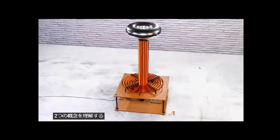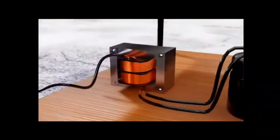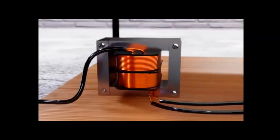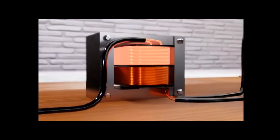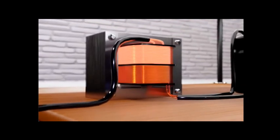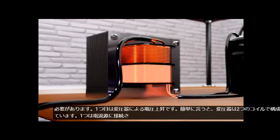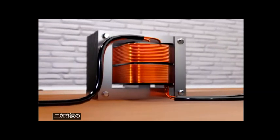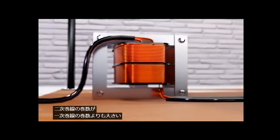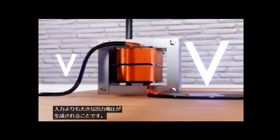The first is the voltage rise through a transformer, which in simple terms is made up of two coils. A primary winding, which is connected to a current source and generates a magnetic flux, and a secondary winding, which converts that magnetic flux into a current again. But the interesting thing is that if the number of turns on the secondary winding is greater than the number of turns in the primary winding, an output voltage larger than the input is generated.